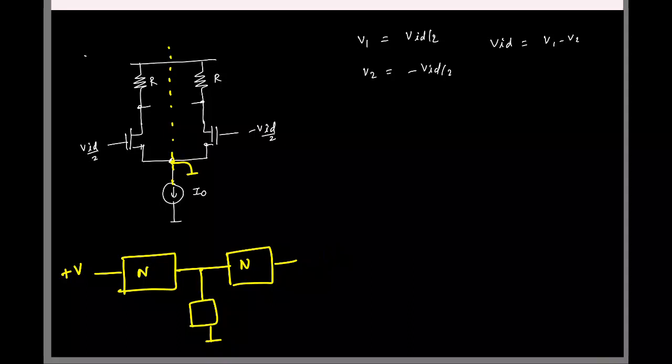So I can use superposition, find the response only due to plus V. Due to plus V, I'll have some, let's say, some K1 times V here. Now I need to find the response due to minus V. The response due to minus V will also be the same, right? Because the circuit is essentially the same, and that's why it is 0.